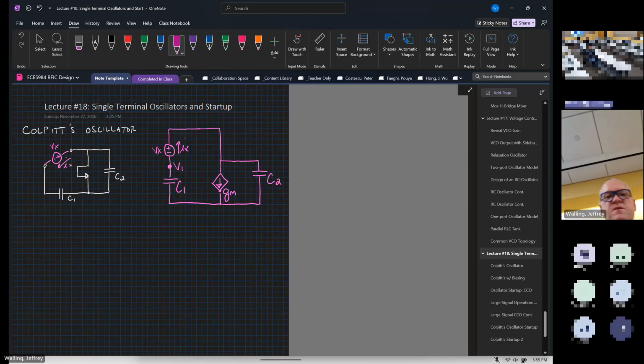Okay, so here's our small signal model. I'm going to say that the value of the voltage here is V2. The value of the voltage here is V1, and the small signal model says that gm times the current is equal to gm times V1 minus V2. That's really the gate to source voltage difference. And then we know that the value above the gate, above the test voltage source, is equal to V1 plus whatever value Vx is.